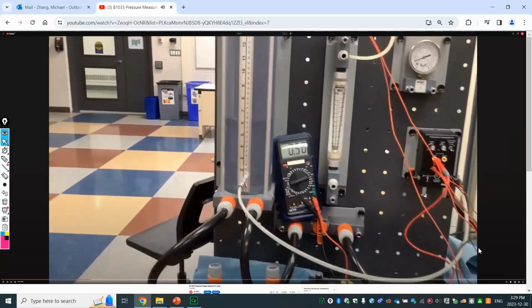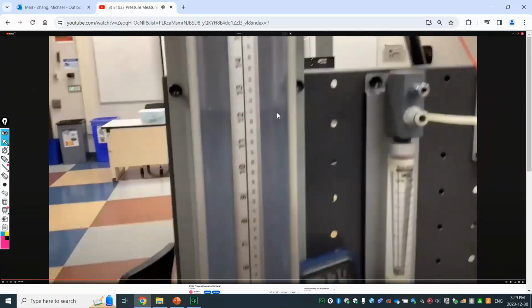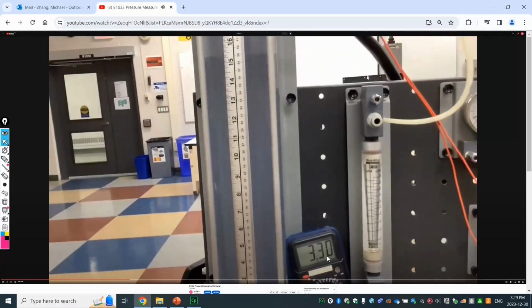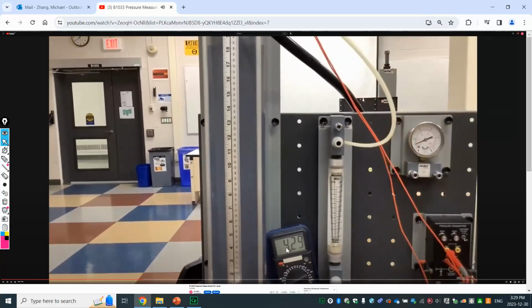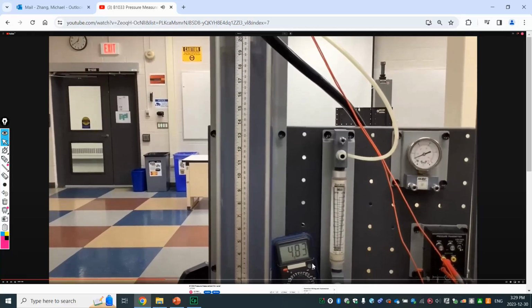Now that's adjusting for the pump. With the pump turned on, you can see the water level reads high. It's going up. You can see the same thing for the output. Before, it was 0.07, and it reaches really high, almost 5 volt. Like I said, in order to make this video shorter, we already started the calibration of this transmitter, so that's why right now it's almost to the top.